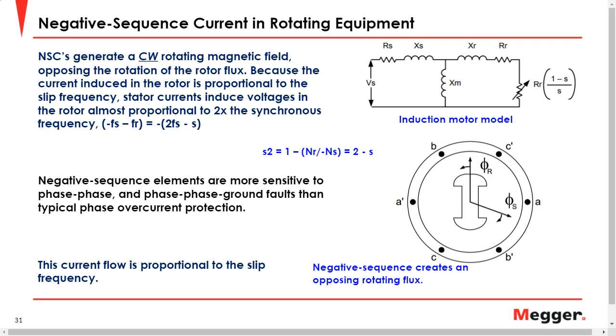You find the maximum difference between one of the voltages and that average, and you divide that by the average. That's one way of doing it. That gives you a number directly from the magnitudes you have in the system, and it's very simple. It's a very effective way of calculating imbalance.